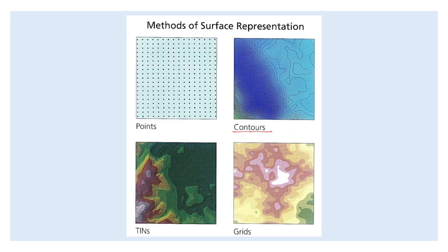Then we'll fill in between wherever it is missing, and using the same point data, we can also create a TIN, which you can see here, and the same point data we can also create the grid, that is the raster image that you've got here. So with just this point data, not much information is present, but using that we can actually generate contours, TINs and grids.